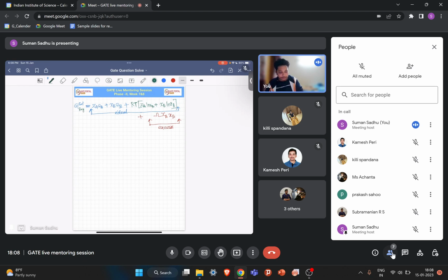Okay, so in case of ideal solution, you had only up to this part. You didn't have that delta H mixing term, because in case of ideal solution, this was 0. But in case of regular solution, you have this extra term in your free energy equation. This term is extra, so that is why it is called excess free energy. So basically, it is written as delta G of regular solution is equal to delta G of ideal solution plus G of excess. Okay, so G of excess is omega xa xb. So everyone understood up to this part?